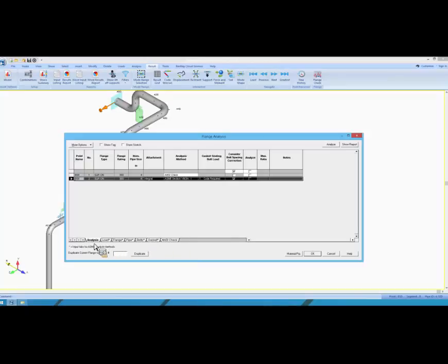We have the analysis tab as the first tab. We have load, flange, pipe, bolts, and gasket. The names are self-explanatory. The loads deal with defining the load. The flange deals with selection of the gasket, the flange material and dimensions. And we would go through the rest of the tabs once we go into the design of an ASME Div 1 flange. So you have some further options here.